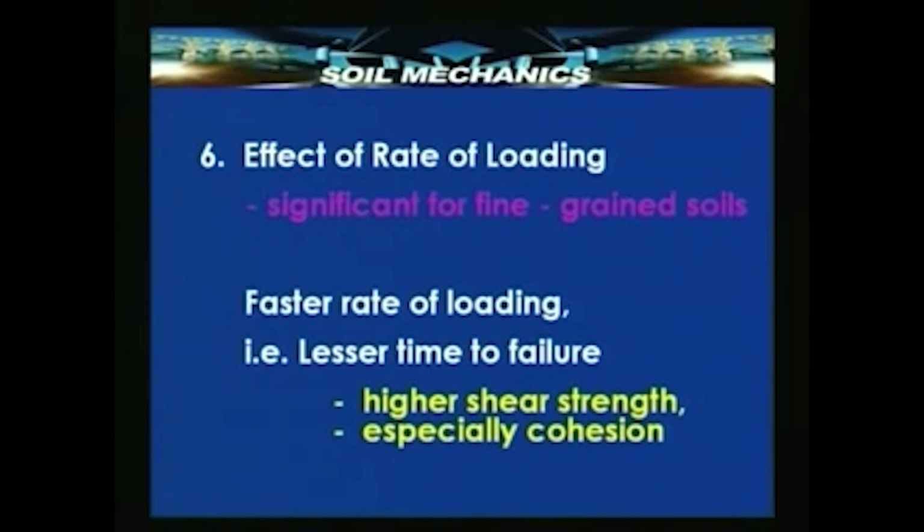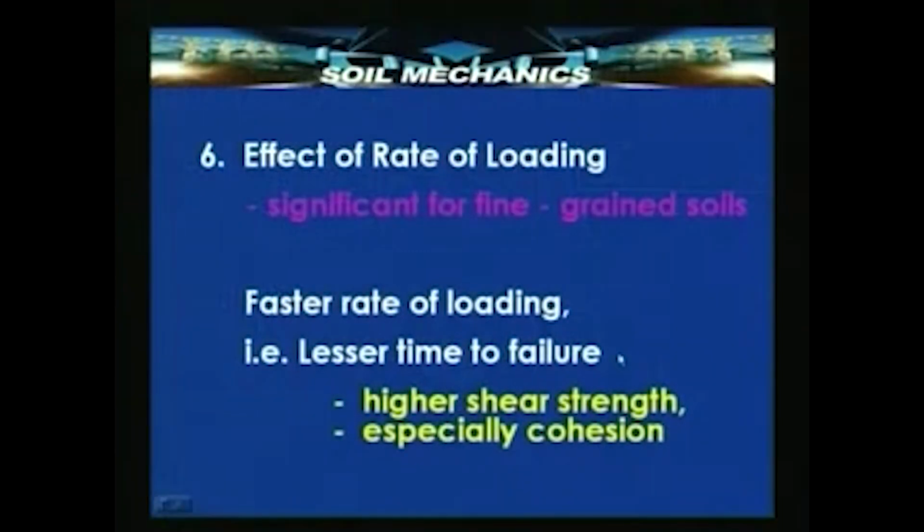The rate of loading is extremely important because the so-called drained or undrained conditions is a relative term, as I have stressed in the last lecture. The loading, if it is rapid compared to the rate of dissipation of pore pressure, then it is an undrained condition. So, fast rate of loading, less time to failure indicates undrained conditions, and therefore it gives a relatively higher shear strength corresponding to the total stress parameters, especially for a value of cohesion.